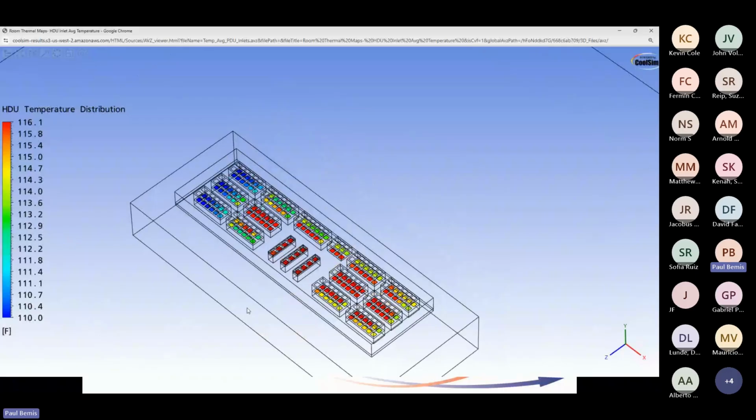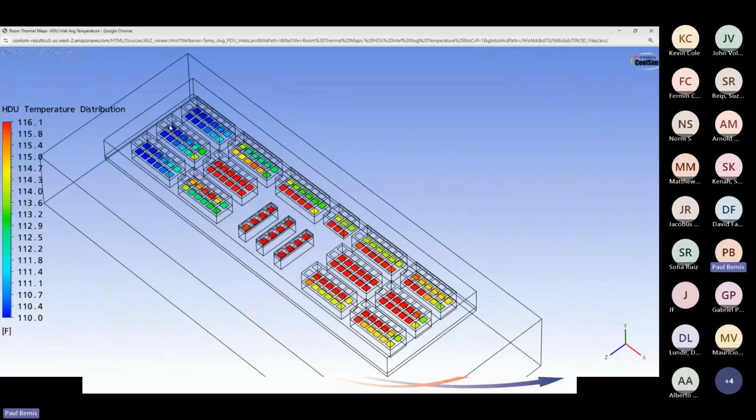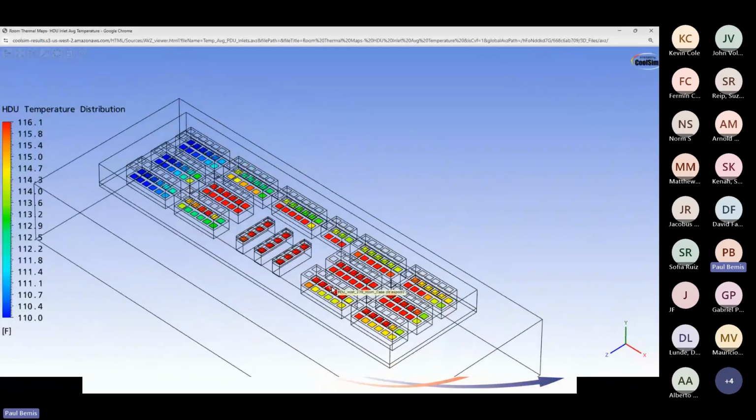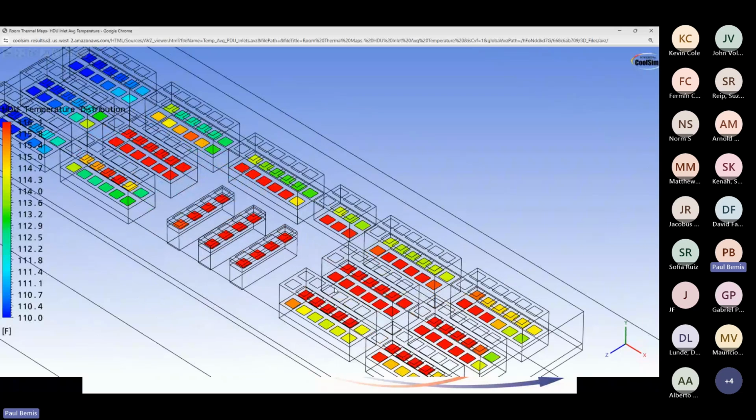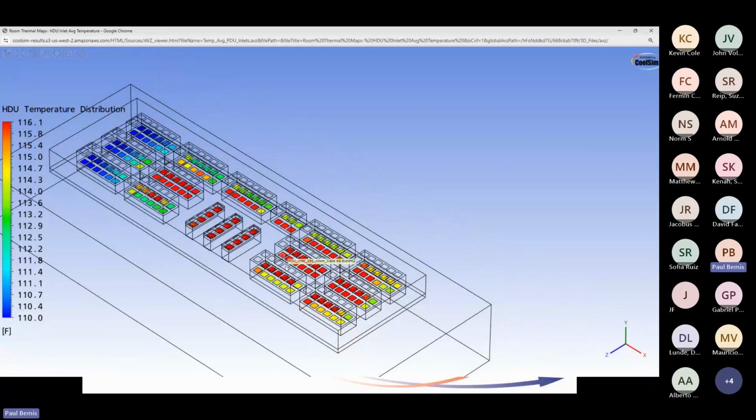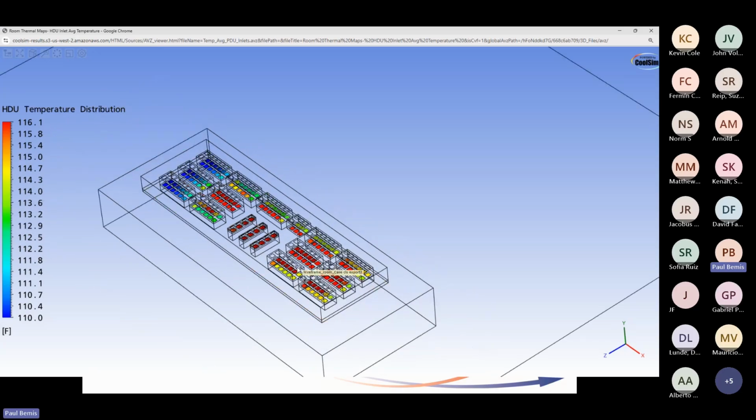But you can see what's happening. So the air is again coming from this direction. Those inlets aren't too bad up front. But as you move downwind, inlet temperatures start to rise. And that's going to cause a degradation in the cooling capacity of these devices. Again, about 1% per degree F. So you see the devices downwind here are running at about 6 degrees higher than the ones up at the front. So I've got about a 6-degree degradation in overall chill capacity of the units downwind. 6% is not that bad. I mean, this one probably is fine.